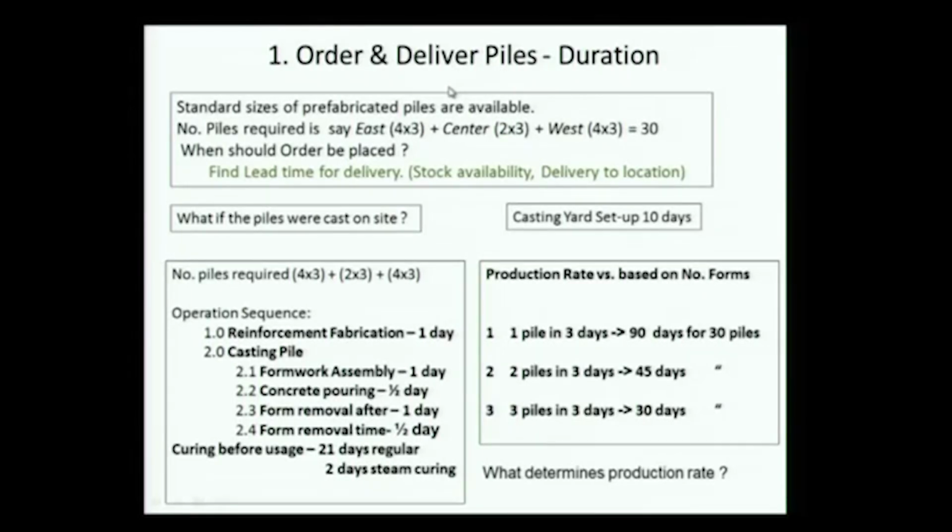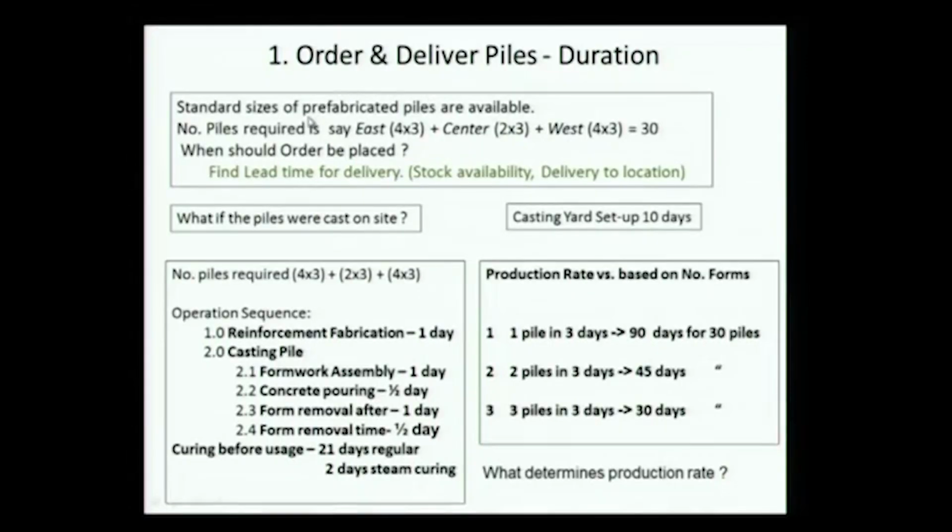Now, how do I estimate duration? Okay, so this slide is a bit busy, but let us see what we can make out as to estimating duration for precast pile. The simplest one is, if I have to order the piles, I have to decide what the lead time for delivery is. If I am going to place an order on a certain item, I have to know. I can't go to the precast yard and say I want 20 piles and he will deliver it to me by evening. It's very unlikely. He will need a certain amount of time because he will have a backlog of orders and things like that. I'll have to find the lead time and then place my order based on the lead time.